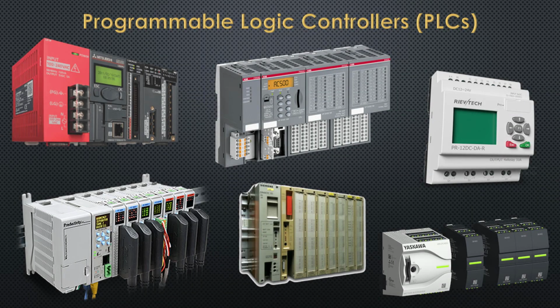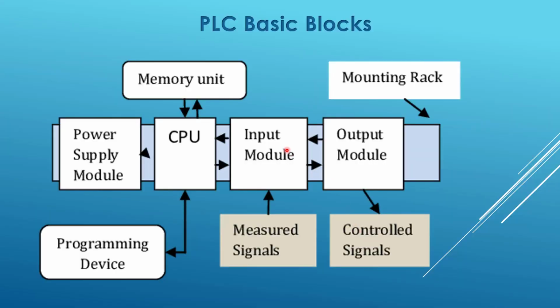Programmable logic controllers. Here we're looking at various types of programmable logic controllers. But with any of them, we're going to have some common features. Now, we talked already about logic systems having an input, an output, and in this case, the logic or the decision making is done here by the CPU. Now, this has some other peripheral devices. We've got a power supply module that supplies power to these. This is typically mounted on a rack, and these are plug-in modules.